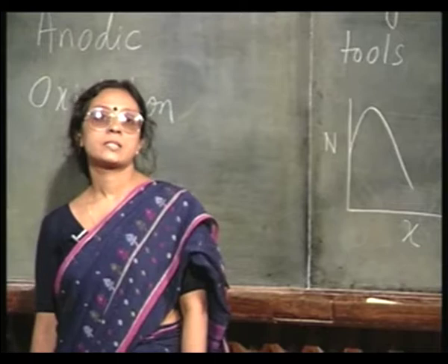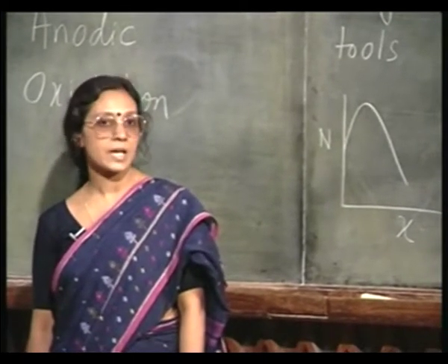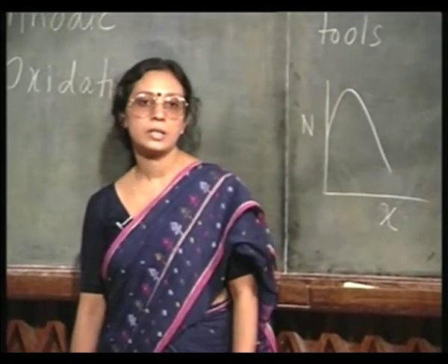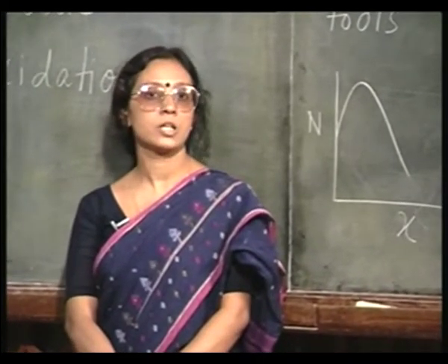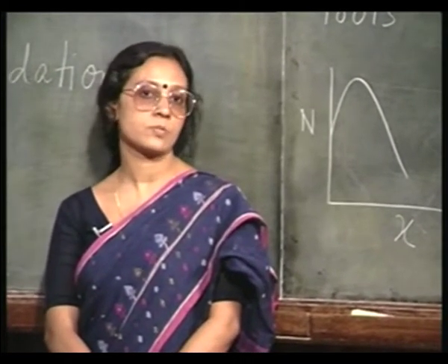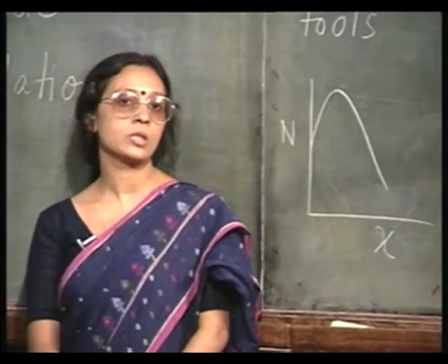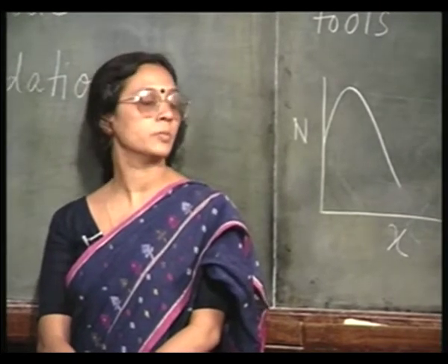But it is very difficult to etch silicon in a precise controlled manner. So, what is done is you grow a thin layer of oxide, and you know 100 angstroms of oxide consumes exactly 45 angstroms of silicon. So, you can etch 100 angstroms of oxide. So, that means we have gone inside by 45 angstrom and again measure the properties.